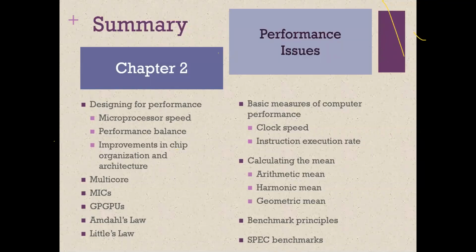Okay. At some material point, when we enable interrupts, then there would be the fetch cycle, then the execution cycle, and then the interrupt cycle. In other words, after the completion of a particular instruction, the instruction will not be deemed complete until the system checks, is there any interrupt request?